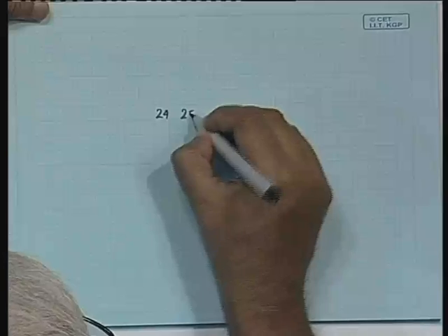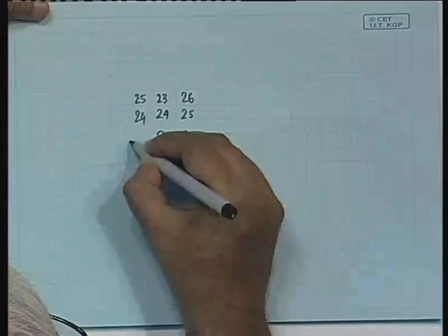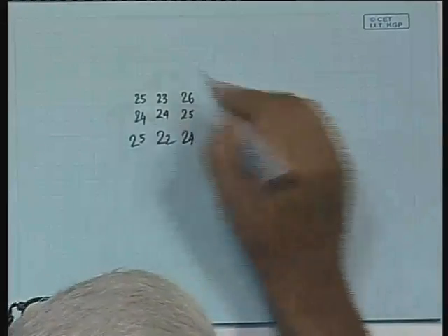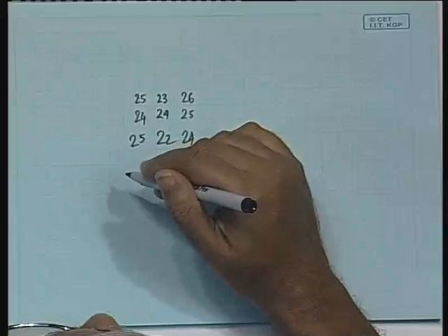Now, how are the two redundancies made use of? To make use of the statistical redundancy, it is definite that we have to do some kind of number jugglery. Number jugglery means that wherever the numbers are quite similar, if we have a patch of image where the pixel intensity values happen to be like this: 24, 25, 23, 24, 25, 22, 24, 25. You can see that the average intensity may be of the order of 23 or 24, and there is a small amount of variation. So, we can have a DC representation which will say that the average intensity of this is, say, 23 or 24, whatever it comes to.